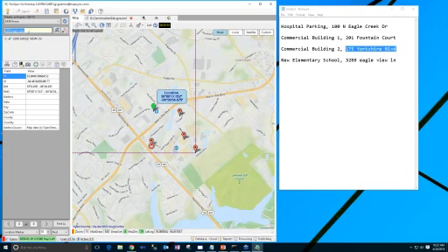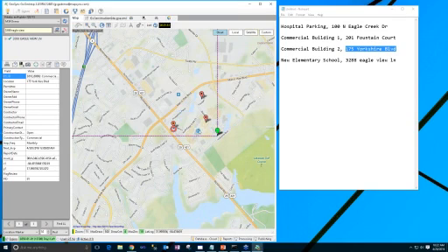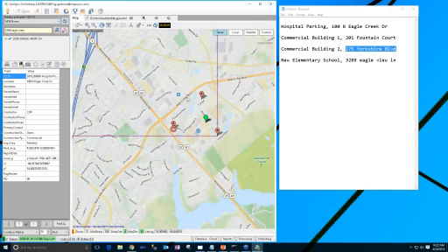If you want to use the address tools, then you can type in an address. You go to the address, and it will automatically create a user marker for you, and you're ready to go ahead and add a feature. If you identify a point feature and you'd like to link some media to that, photos or documents that you want for reference purposes, then you can go to the Media tab and add that information.